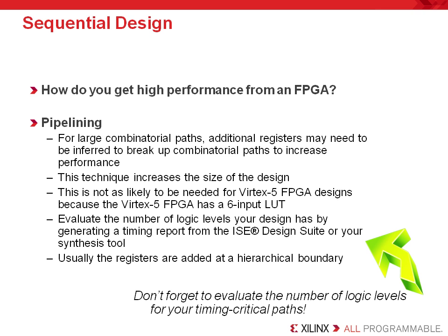Incidentally, pipelining has been so essential for gaining speed in FPGAs that every LUT in an FPGA has an associated register with minimal routing delay. This also explains why the logic cell is the preeminent benchmark for device density. So keep in mind that you should always evaluate your worst-case timing path with either your synthesis tool, that is your schematic viewer and the use of timing constraints, or by evaluating your timing with the Xilinx Timing Analyzer utility that is included with the ISE design suite.